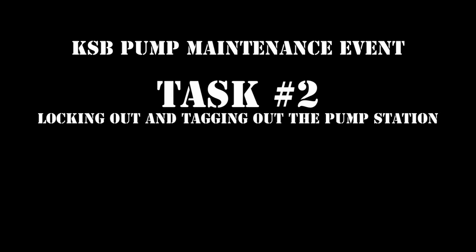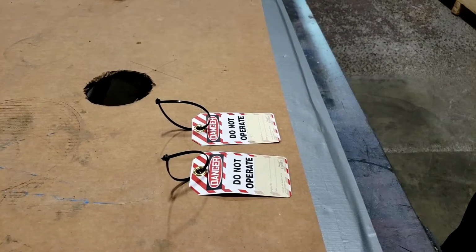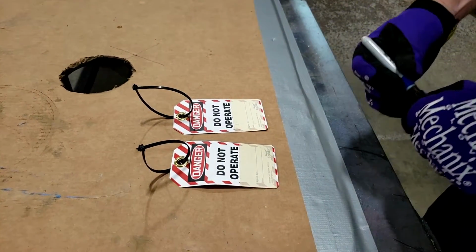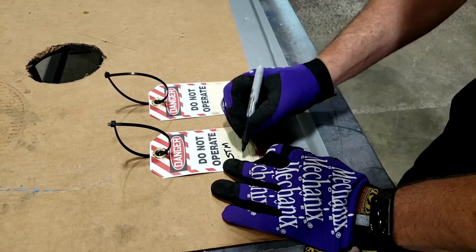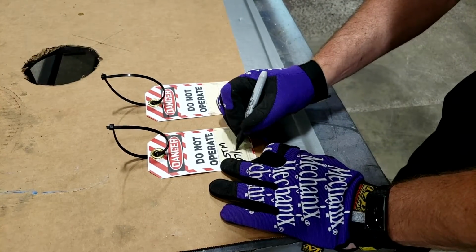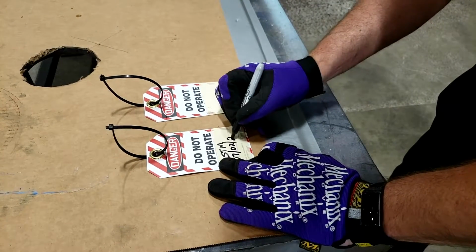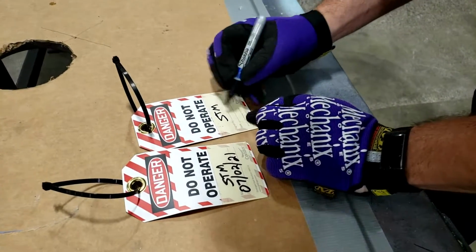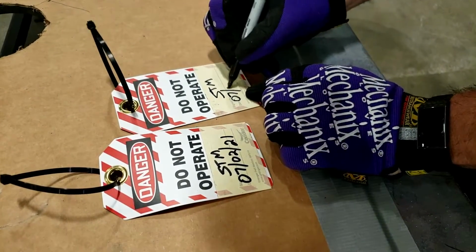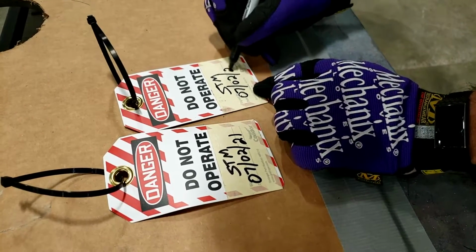KSB Pump Maintenance Event Task 2. Locking out and tagging out the pump station. The safety supervisor must write the date and their initials on the label on the lockout tags with a Sharpie marker. It must be legible. It must be written on the white label and not on the tag itself. The date must be in the following format: month, day, year. The date written on the tag shall be the actual date you are doing the event.